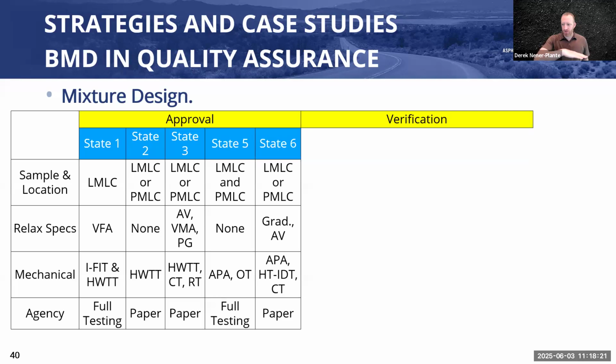many agencies, if you just start with what we do now, some agencies test mix without reheating. They have a presence at the plant. Obviously, the contractor often has a lab at the plant. They test mix while it's hot. And then maybe some owner comes down and takes a sample, it cools off, they reheat it later, they test it. And for the most part, we have systems that can accommodate those two different specimen fabrication procedures for asphalt content or whatever you want.